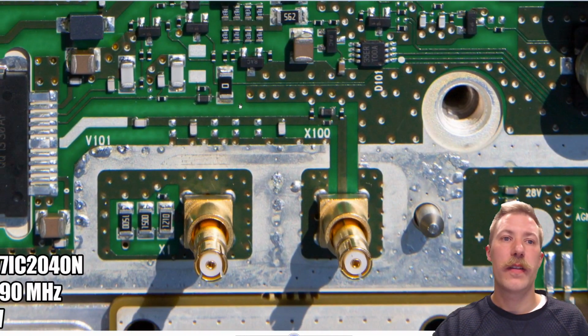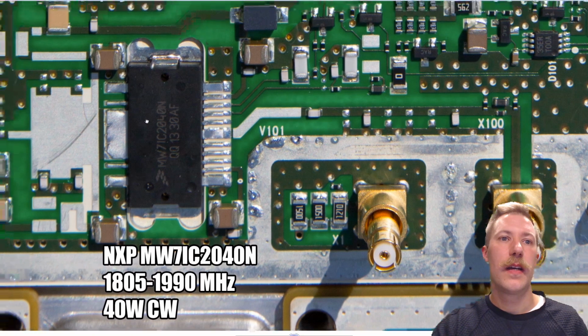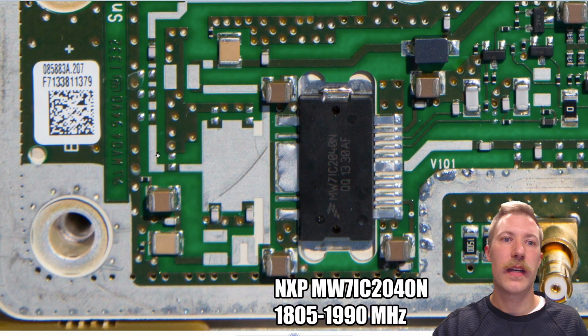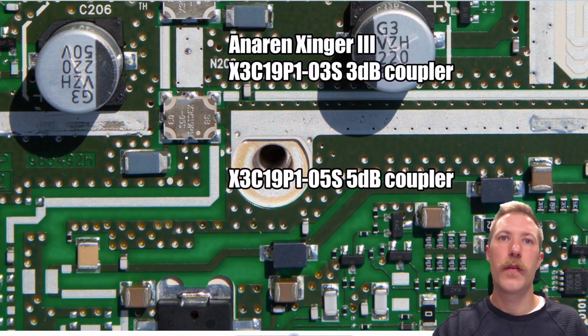Now, if we follow the signal path down here from the 2 golden connectors, it first enters the first NXP amplifier here, which is a pre-amplifier of just shy of 40 watts. As we can see, it has really heavy power supply decoupling sitting around the corners. From here on we still have a single signal line going up here, going through the first